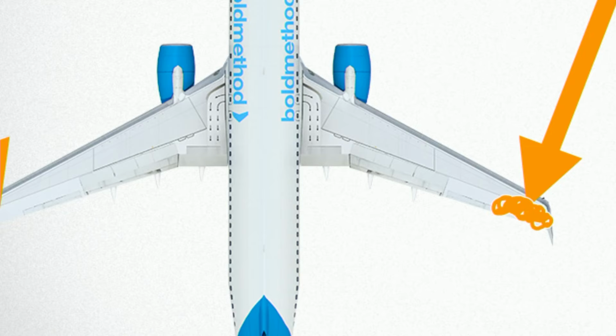Normally, we design aircraft so that they stall at the root of the wing first. But when you end up with a lot of spanwise flow, it tends to stall from the tip of the wing first. And the problem with that is that's typically where your control surfaces are, so the aircraft can be very difficult to control as it goes into a stall. So that's another downside of swept wings. Okay,